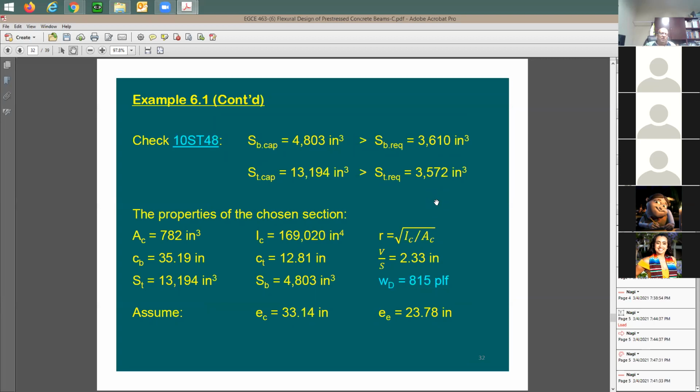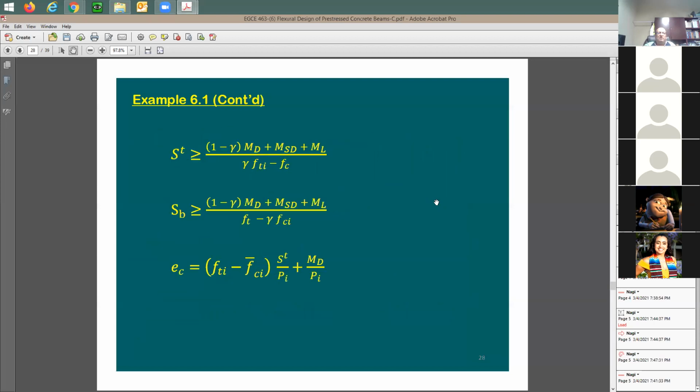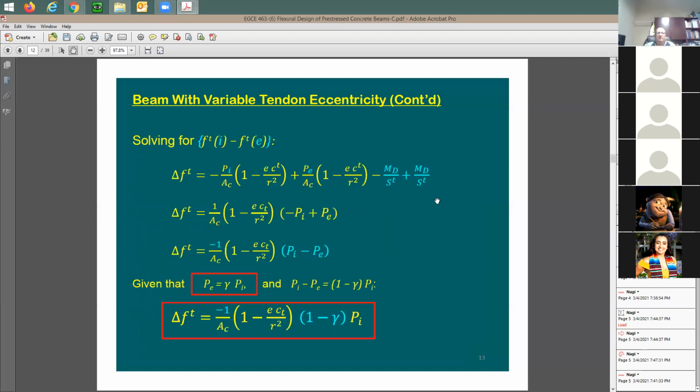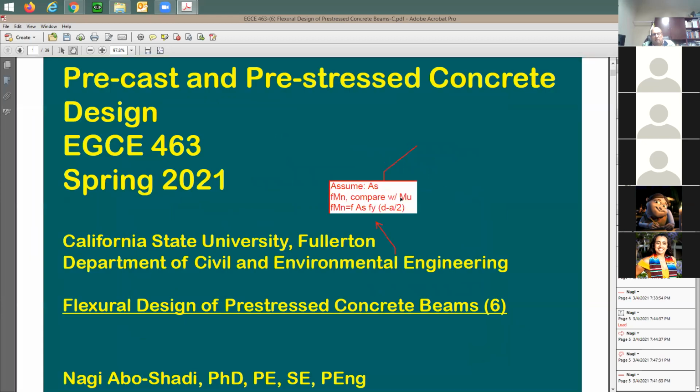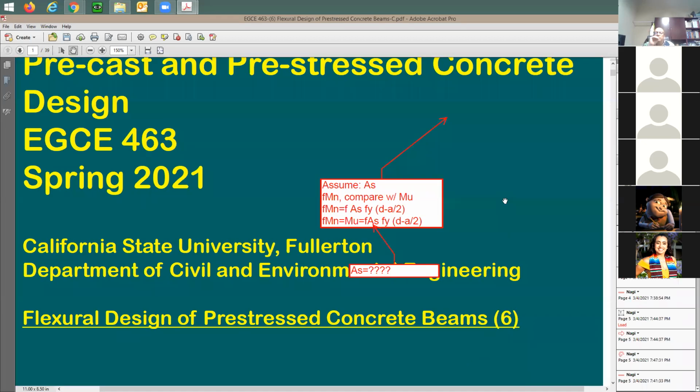And instead of having all the stresses calculated out for you, you're going to have something to take you to the section you need. This here reminds me again of the concept that I went with at the beginning. I said we have two ways of design when you have a conventional concrete beam. One method, you throw the rebars, which means that, now if I take it here to this pre-stressed thing, I'm going to say, you pick any section you want. And then you put in your equations. And then you check the stresses top and bottom.